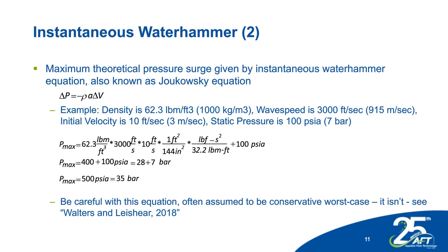Something to caution engineers on, and certainly when I first learned the Joukowsky equation many years ago, it was taught to me as being, as the top bullet alludes, the maximum theoretical pressure surge. And if you use this equation, you always have a conservative answer, and you cannot exceed this. This is actually not true, and so you should be careful with this.